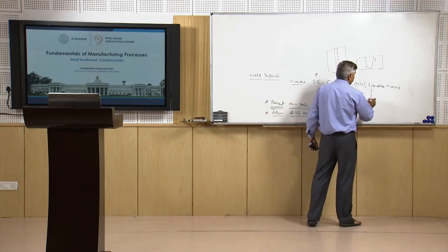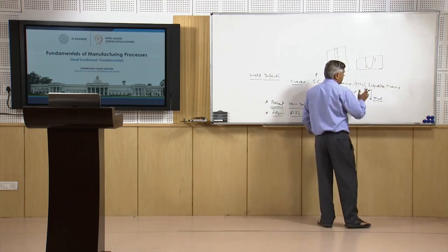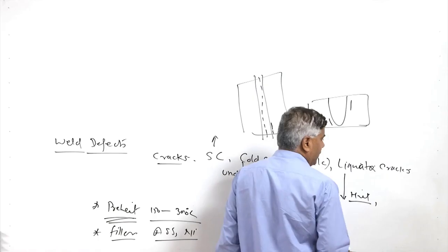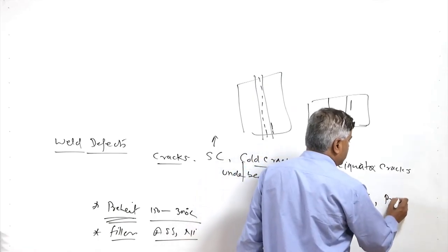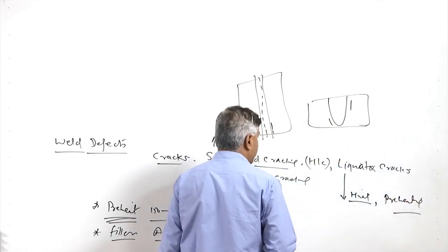Reduction in the heat input is basically used because, as I have said, liquefaction cracking is caused by the wider solidification temperature, and so limited heat input is one of the methods. Preheating also helps in reducing the liquefaction cracks.